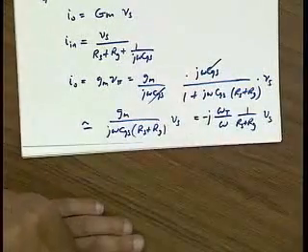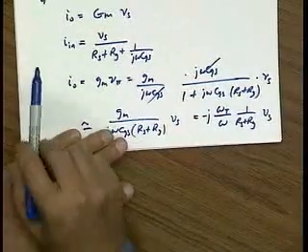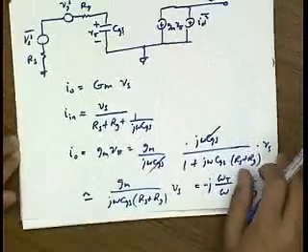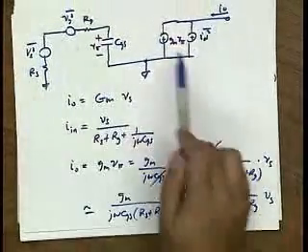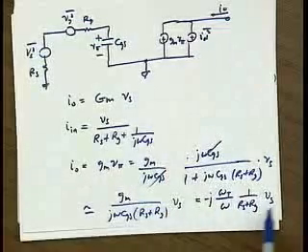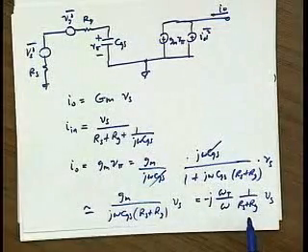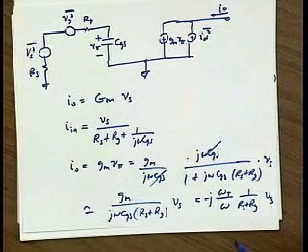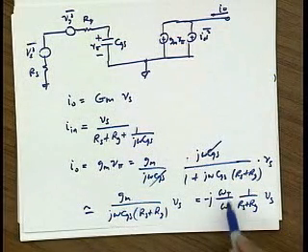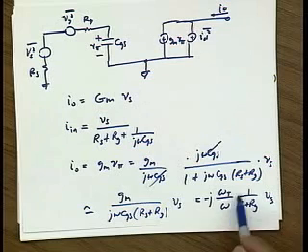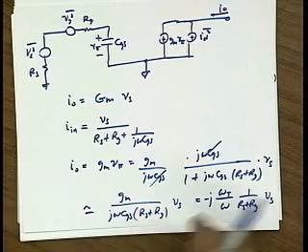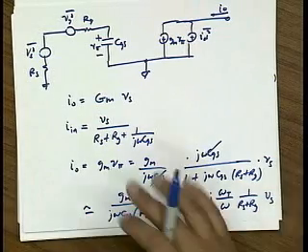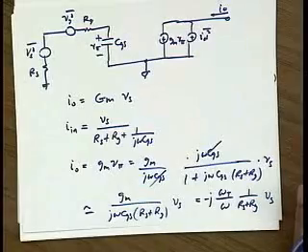Okay? So this is the current gain of the device, or the transconductance of the device. Basically, a voltage on this side produces a current on this side by capital Gm. So it's interesting to see at high frequencies, the Gm of the transistor effectively is a ratio of omega t to omega times basically 1 over the source resistance, assuming Rs is bigger than Rg. Okay. Now this way of thinking is going to come in handy later on.